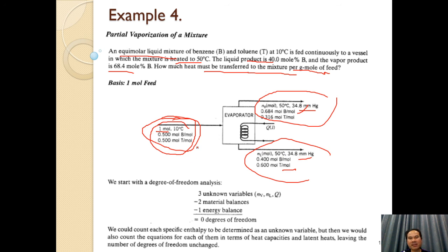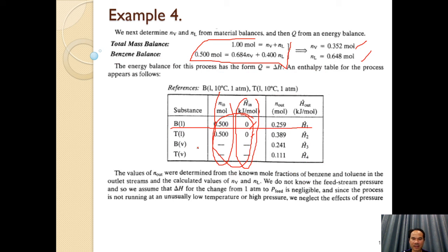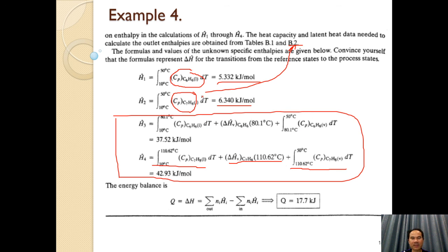You have to change it, but the pressure change is a very small value. You can neglect that. And S2 also has a pressure change, and S3 has a pressure change in this term too, but the change in pressure is a very small value. You neglect it, and then you get only the temperature change.